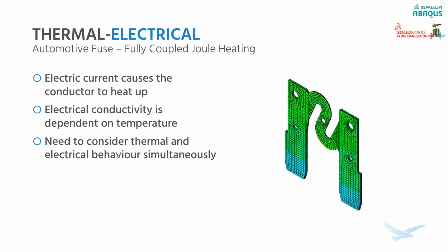The trick here is it usually needs to be coupled together because as the part heats up, the electrical conductivity or the resistivity is dependent on the temperature. And so that's going to change how the electrical current moves through the part. So we need to look at them both simultaneously. Needs to be done as a fully coupled Joule heating problem. And this can be done in Abaqus if you're looking for an FEA approach, or it can be done in flow simulation if you have some convection to consider as well.